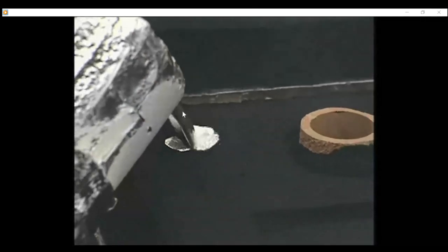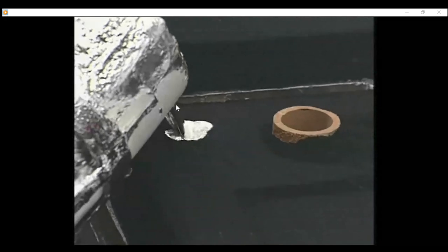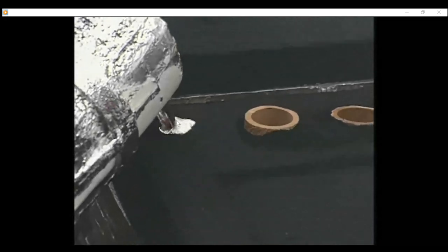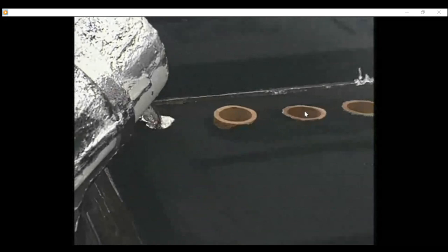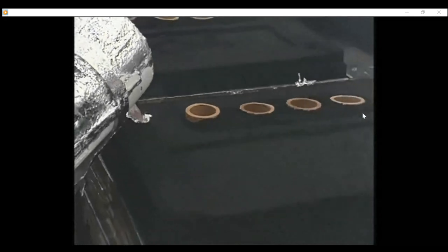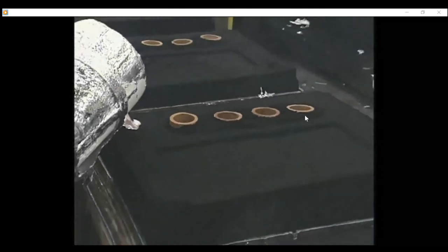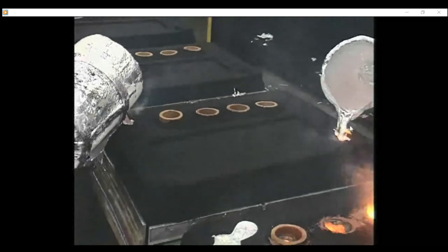Later when they remove it, then you put the liquid. This is a sprue, this is the liquid. You put the liquid metal. It is aluminum liquid. They put liquid metal here. This is the open riser actually. Can you see that there are many open risers. It depends on the shape.